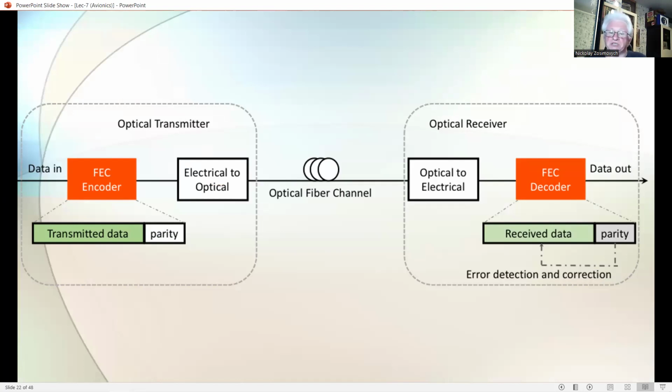The optical transmission media is unaffected by EMI, and very much higher data rates can be achieved, like gigahertz bandwidth, like 10^9 Hz. Current avionic data bus systems using fiber optic data transmission operate in the 20 to 100 megabits per second bracket.